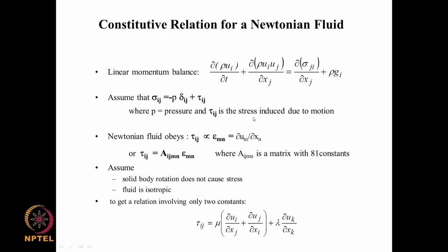And we studied the kinematics of deformation, and we suggested that the deformation rates can be expressed in terms of linear combinations of this deformation tensor, and we seek a linear relation between the stresses that are induced by relative motion and the strain rates that are produced as a result. Since these strain rates are expressible as a linear combination of the velocity gradients, you could replace the stresses by the velocity gradients, so that we can get rid of all these unknowns.